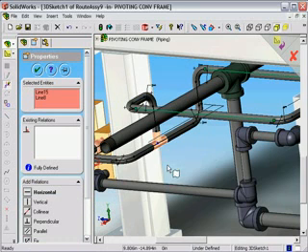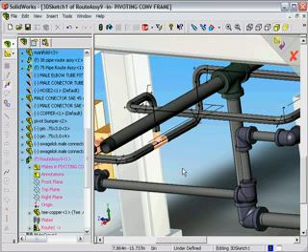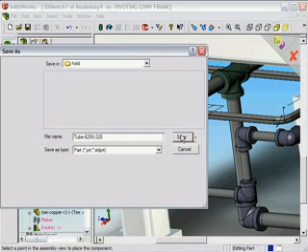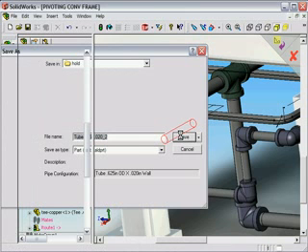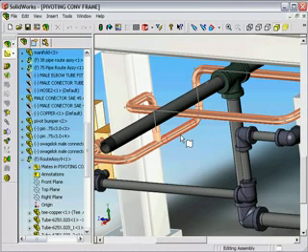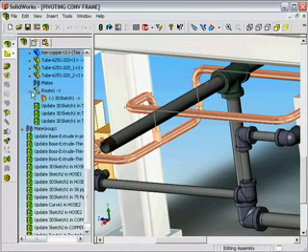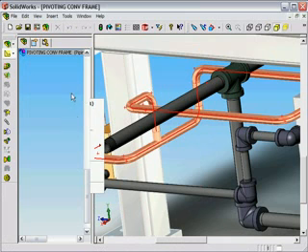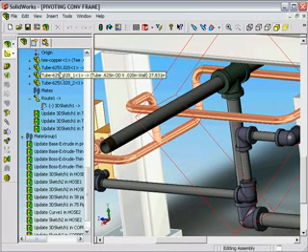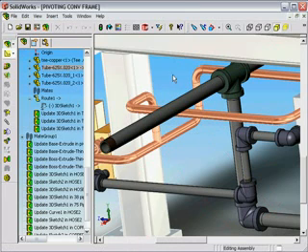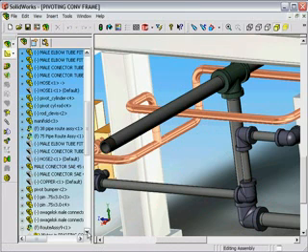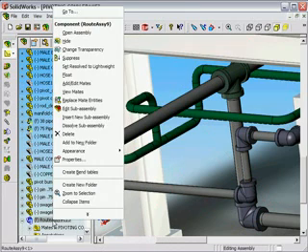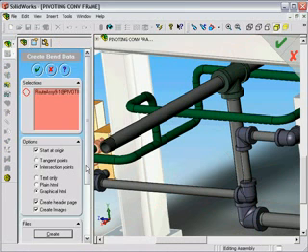At this point, we're done with the routing of our rigid tubes in SolidWorks. So we'll go ahead and actually save off our tubes as individual SolidWorks part files. Now, one of the great things about SolidWorks Routing is it's giving us information necessary for manufacturing. You will see in the feature manager that we actually indicate the length of each tube right on the screen for the user. SolidWorks Routing also provides the capability to generate the bend information for rigid tubing.